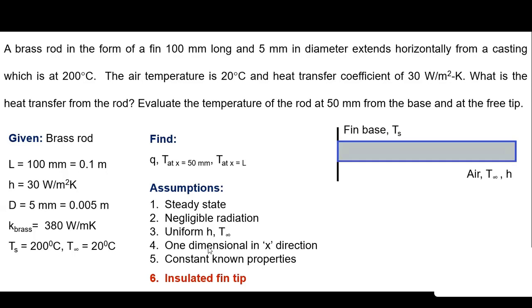So let us assume certain things: steady state, negligible radiation, uniform value of h, one dimensional conduction in x direction only, constant properties, and finally the fin with insulated tip. So with this assumption, let us try to solve this.